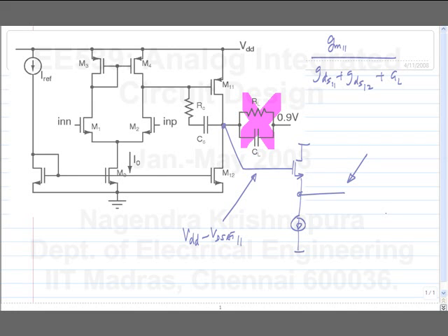So, if let's say you have a purely capacitive load, okay, that's the extreme case, right? Purely capacitive load, you can get high gain in both two ways. One is to make, let's say, a telescopic folded cascode op-amp. Let's not go to telescopic because there we know the swing is going to be relatively small, right? In a folded cascode, you do get high swing, not as high as this, but high enough.